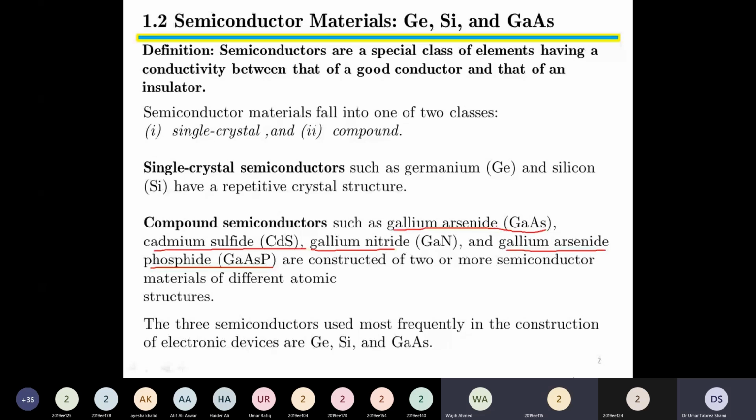Sir, which one is the less power absorbing? Most power efficient is gallium arsenide. In terms of power, gallium arsenide. But gallium arsenide is much more difficult to manufacture as compared to single crystal semiconductors. We need much more intricate processing procedures to make the compound semiconductor. So as a result, the burden will be borne on the price of the manufacturing process.